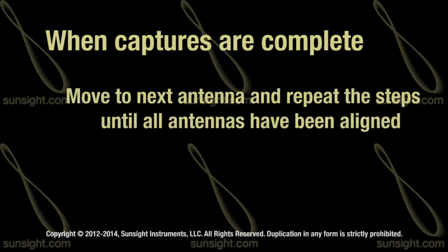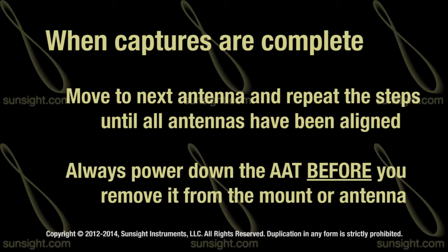Once you've completed the captures on the current antenna, you can move on to the next sector and repeat the steps to capture the measurements for that antenna, and so on. Remember to power down the AAT before removing it from the mount or antenna.